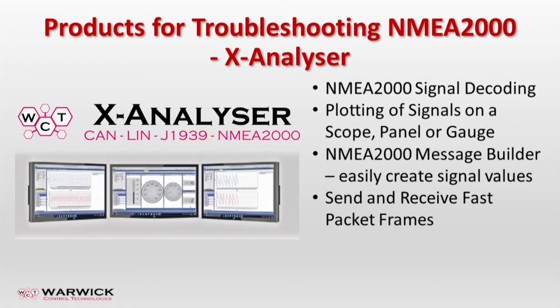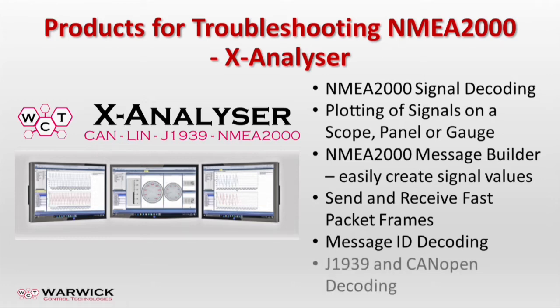There's built-in decoding of the NMEA2000 CAN message identifier, broken down into PGN, source address, priority, plus more. And then the professional version also comes with decoding for J1939 and CANopen. Have a look at the feature comparison here.